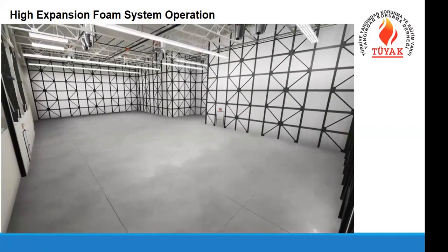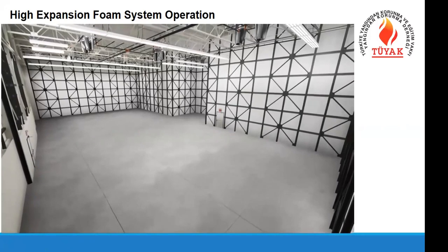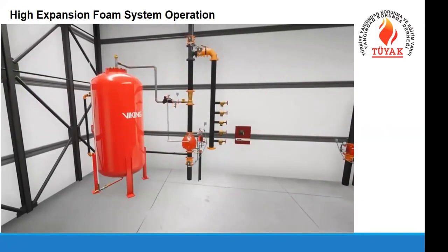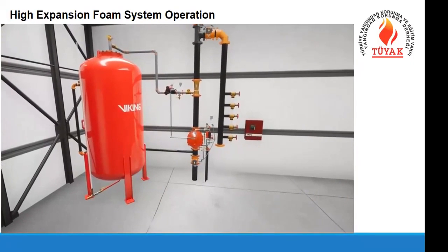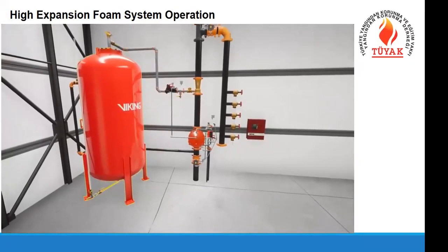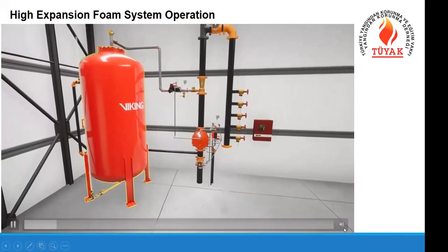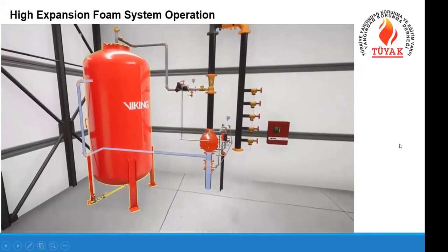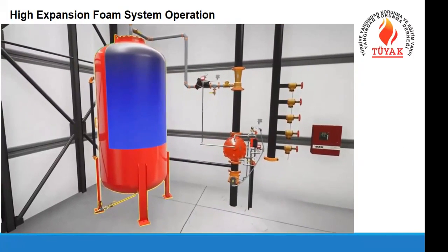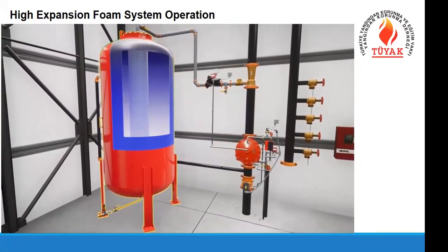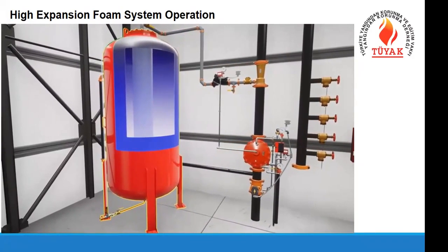In this scenario, we are looking at a Group 2 aircraft hangar. The hangar is protected with an electric release deluge foam system supplied by a bladder tank. A bladder tank is a device that is continually pressurized by the main water supply. The water sits between the steel shell and the rubber bladder. The bladder is filled with a foam concentrate.